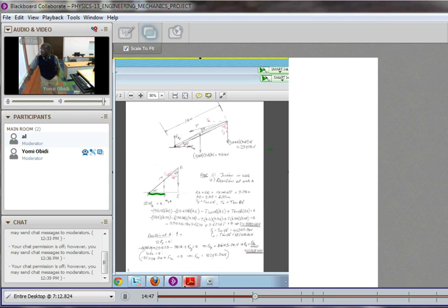This is AD. AD is half. It's just going to be half of this entire length from the arrangement that we have. So we know the length of AD. We also know, this is actually some necessary bookkeeping, TY, because T has its component in the X and Y direction. TY is just T cosine 60 degrees, and TX is T sine 60 degrees.